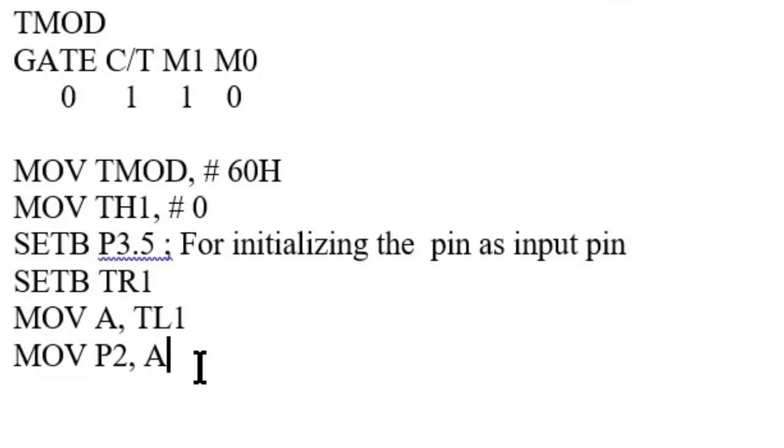Next, for completing the program, what is needed? We should check the timer overflow flag. So the same instruction, JNB TF1, here, and the label here is in this position.